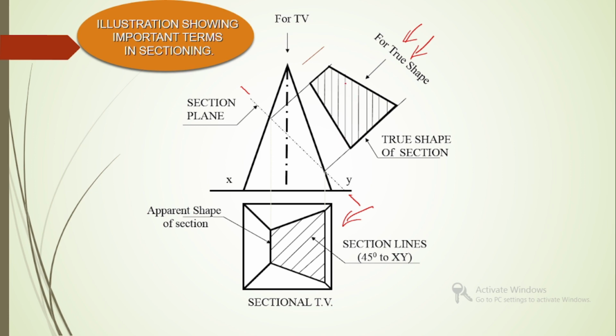And we must hatch that true shape in such a way that the section lines, the inclined lines, must be inclined 45 degree with the corresponding xy line. That means here, the corresponding section plane. This angle must be equal to 45 degree. Those are the important terms in sectioning.